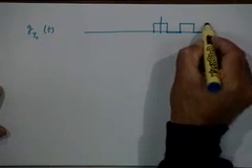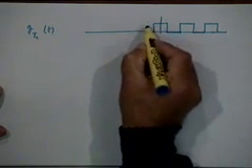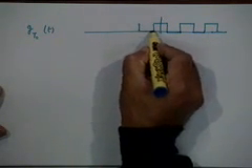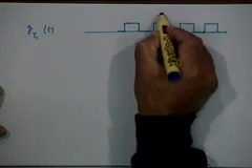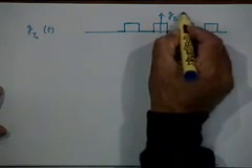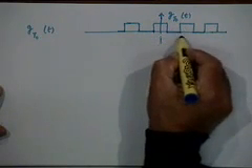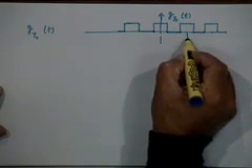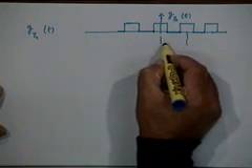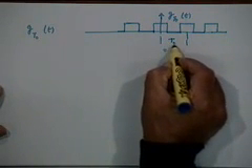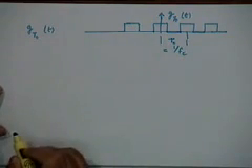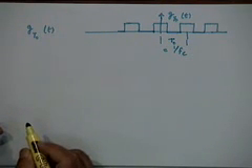So basically this is the kind of function with which you are multiplying the input voltage, which is the c(t) plus m(t) waveforms. This is the nature of g(t), where the period of this waveform is T0, which is equal to 1 by f_c, the carrier period, right.